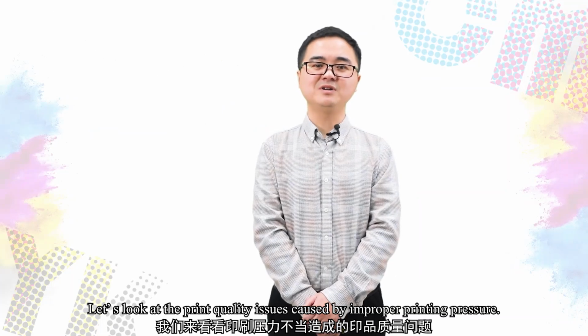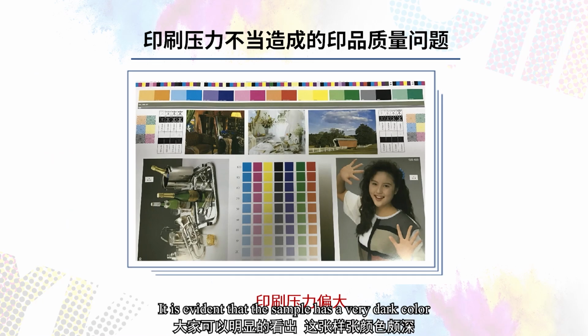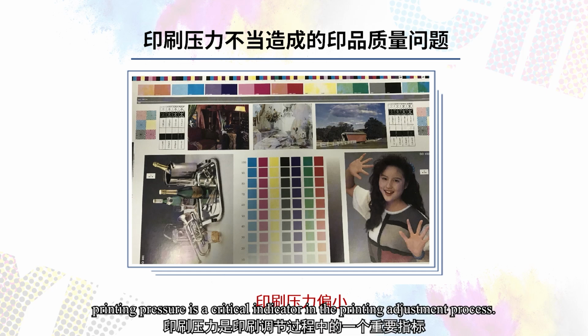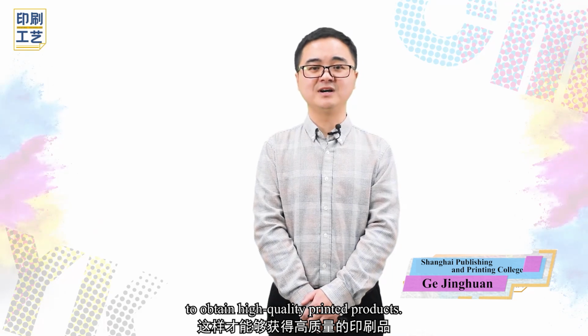Let's look at the print quality issues caused by improper printing pressure. This is a printed sample with excessive printing pressure. It is evident that the sample has a very dark color and severe loss of detail in the shadow areas, resulting in unsatisfactory print quality. This other image has relatively light colors and small dots, also indicating low print quality. Therefore, printing pressure is a critical indicator in the printing adjustment process. During printing, we must ensure reasonable printing pressure to obtain high-quality printed products.